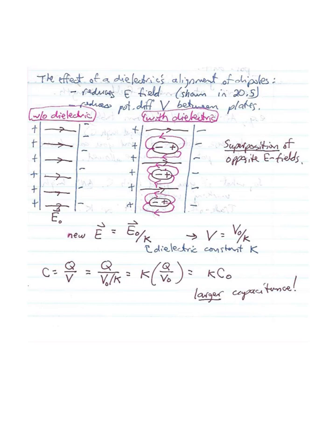And so what this ends up being is the capacitance that, remember, is determined by the area divided by the distance between the plates, but now it's being multiplied by something, and that something is always going to be a number greater than 1. So the effect of having a dielectric in the middle between the plates is to have a larger capacitance.